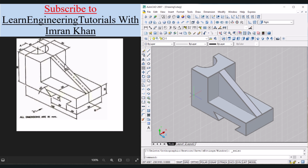The first two lines, they are center lines, and these two lines, they are solid lines. So click on line, track this midpoint and click on this midpoint, click on this midpoint, move in this direction, click, and then move in this direction. Here we can see the tracking line, so click, press escape.